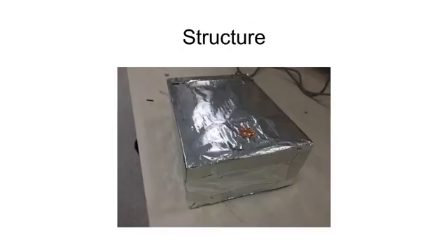And the structure of my cavity resonator is like this. I have coated the cardboard with aluminum foil, and I use aluminum tapes. The reason for that is to make the propagation of waves as perfect as possible, because if I use normal rubber bands, they are non-conductive, and they will prevent the surface current on the cavity, which also affects the propagation of electromagnetic waves inside the cavity.